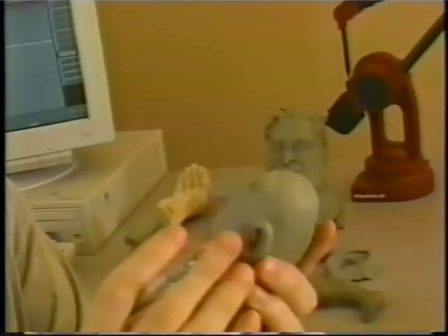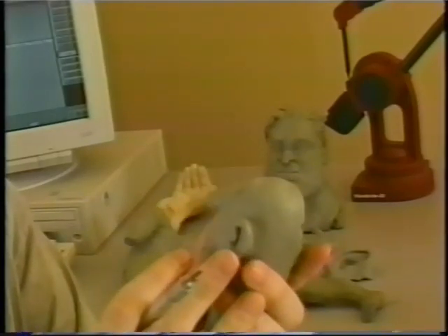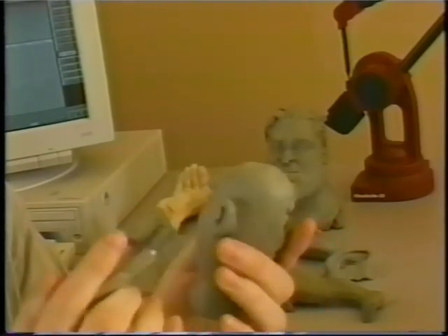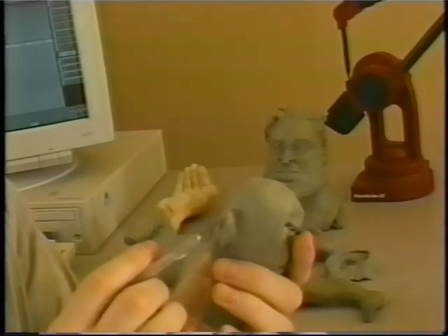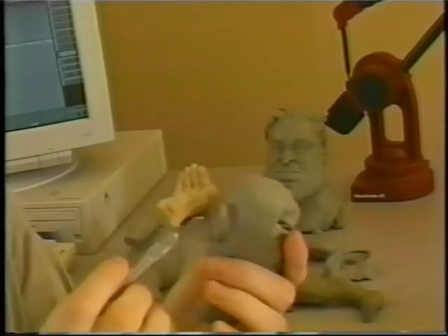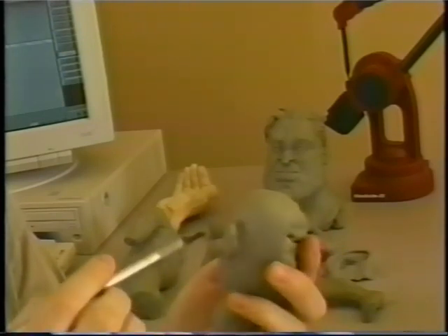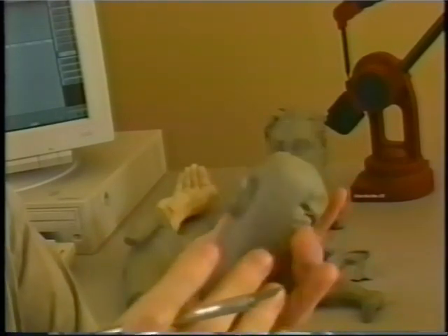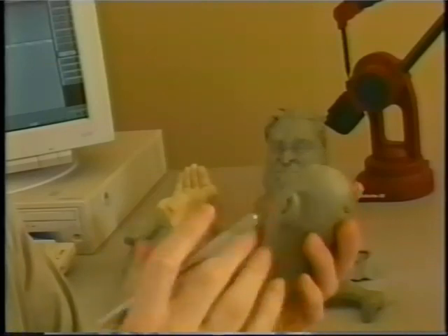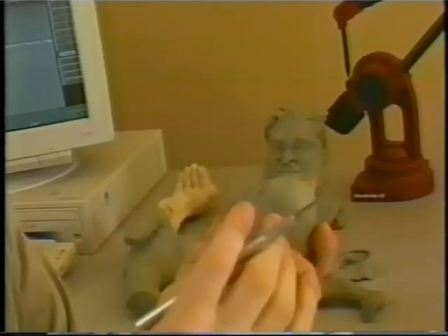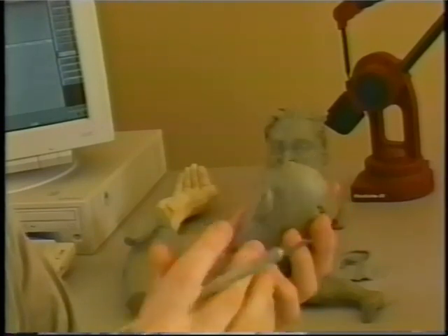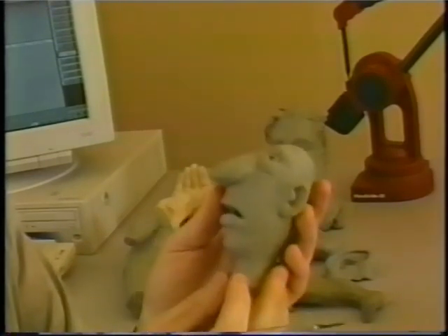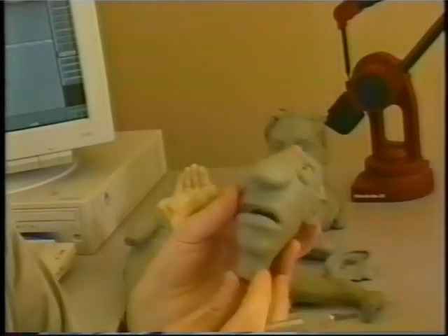That is that the more surface you cover with the NURBS surface, or the more area of your model, the more dense and the more complex it has to be, because the most complex part has to be defined, and all that extra data goes all around the rest of the model. So for instance, you have to have a lot here in the mouth. Well, that's going to go all the way around to the back of the head, whether you need it or not in the back of the head. Same thing with the ear. If you were to include enough geometry to really capture this shape, you'd have a bigger mess of points. So the smaller area you can define with a NURBS surface, the better it's going to be, or the easier it's going to be to edit.